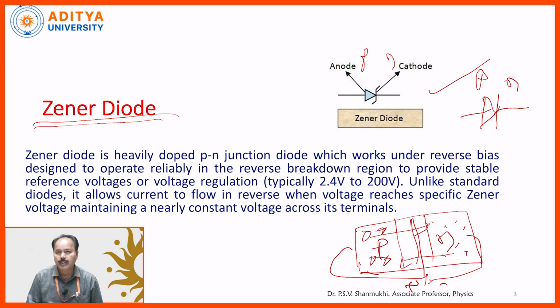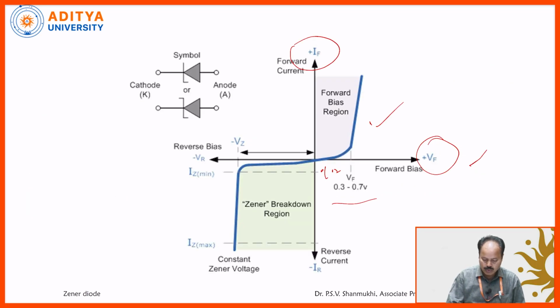When you increase the voltage up to a certain value, almost no current flows while the barrier width gradually decreases. At a certain voltage, the barrier vanishes, and that is why the current suddenly rises sharply. So, this is the forward VI characteristic.